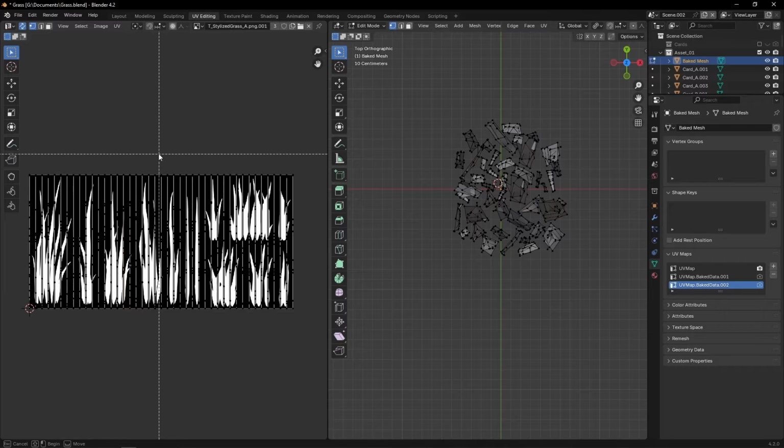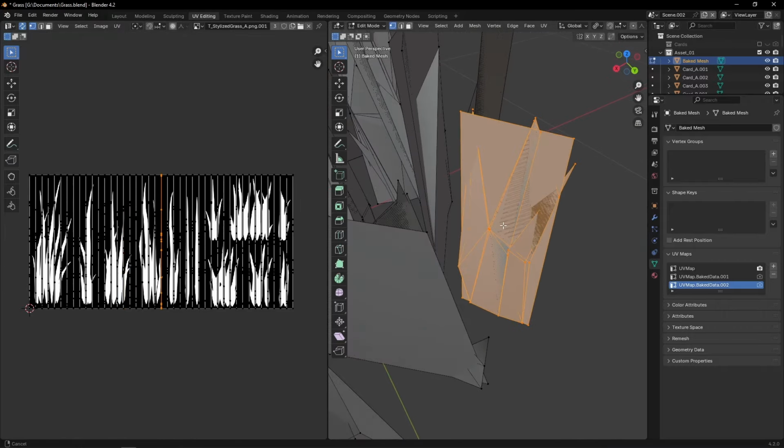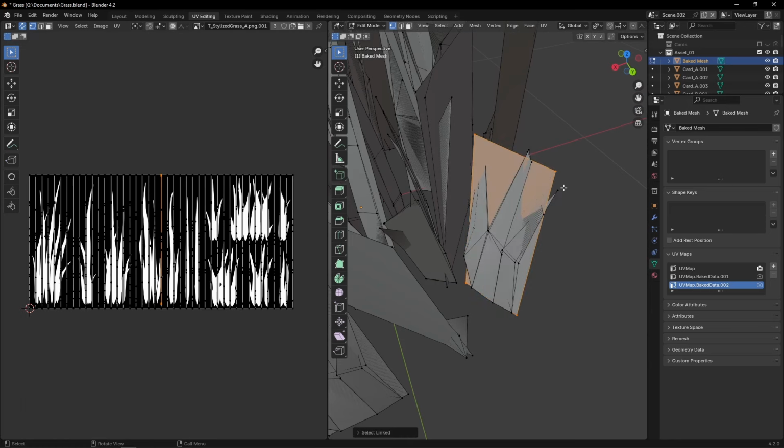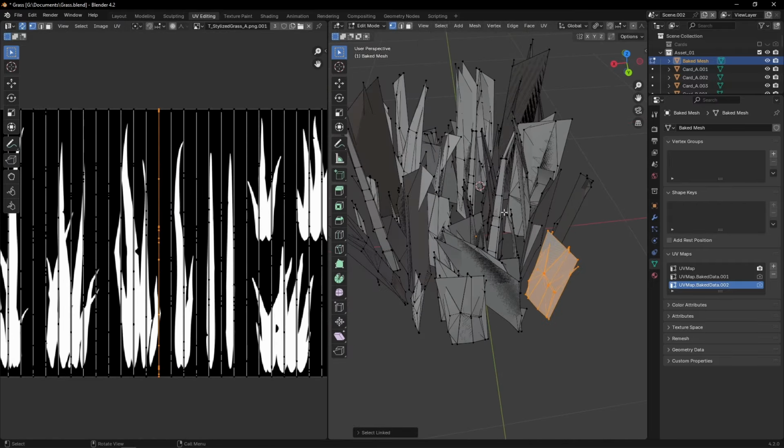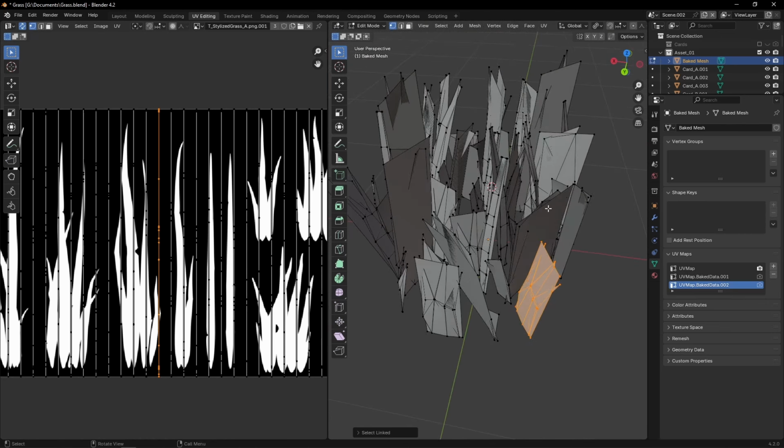So having separated LODs into different objects would have generated a different random value per LOD, and that'd be hugely problematic. Say I use that random value to offset the wind animation per card. Switching LODs in-game would result in a different offset and a sudden jump in the wind animation, right? So here I kept all LODs part of the same object to ensure they share the same random value, if that makes sense.